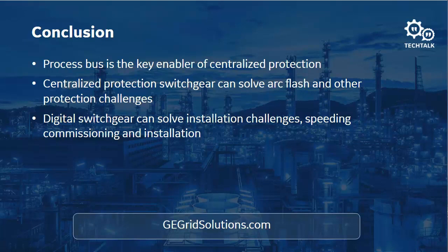It's a very important question because the process bus implementation that I talked about today with the MU320 and the process bus module is using 9-2 LE. Now, it can also use 61869, but both of those, as well as the brick, were defined by the 61850 standard.